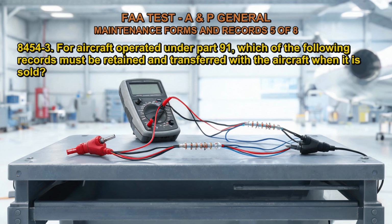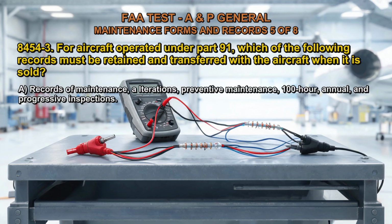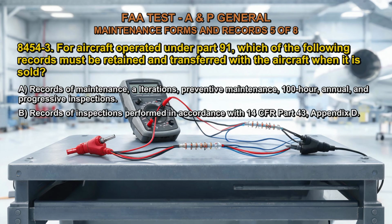Q8454-3. For aircraft operated under Part 91, which of the following records must be retained and transferred with the aircraft when it is sold? A. Records of maintenance, alterations, preventive maintenance, 100-hour, annual, and progressive inspections. B. Records of inspections performed in accordance with 14 CFR Part 43, Appendix D. C. Records of the current status of applicable ADs.